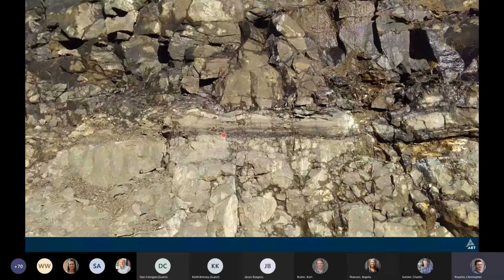But like I said, that kind of answers his question on our petrography, our lithologic identification, kind of answers their question of why they're seeing higher than normal results. A good quality hard basalt will give you really good physical test results. And when they're a little bit higher, somebody who knows what they're doing and looking at those results and seeing those numbers, you can kind of say, well, something's not right. Either our equipment's off, our procedure's off, or the rock is off. So it just gives you some things to double check.